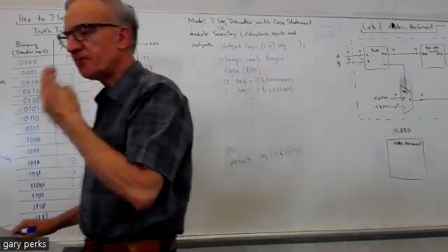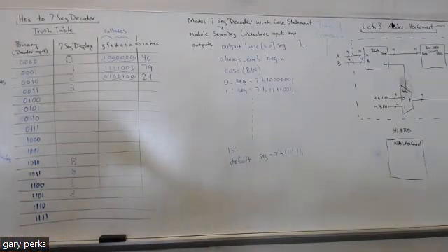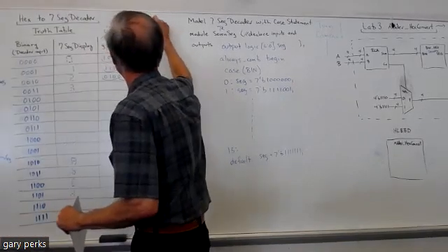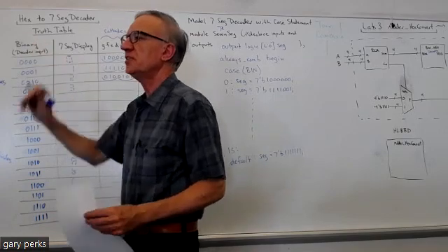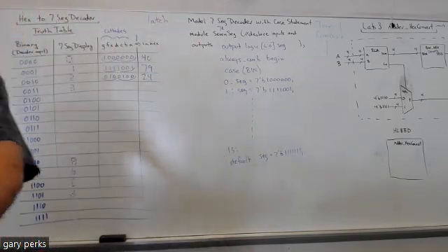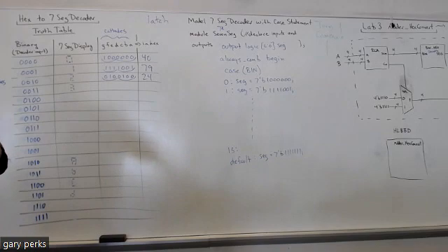The other reason you always want a default is because if you omit a default in a case statement, it's going to create a latch. Okay, you know that word we've been using, latch? I told you, if you get a warning with the word latch, treat it like an error. You've got to get rid of it. Okay, and that's because, and you'll learn more about this in a couple of weeks, a latch is like the main circuitry of memory. So when you have a latch, you have memory, and that's additional circuitry.